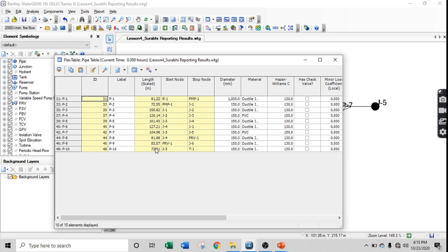So now I want to filter out the PVC pipes, as we have assumed a situation that in 5 years only the ductile iron pipe material will change its constant, which is the Hazen-Williams constant, C factor. So I will just filter the PVC out of this column and we will be remaining with only the ductile iron pipes.